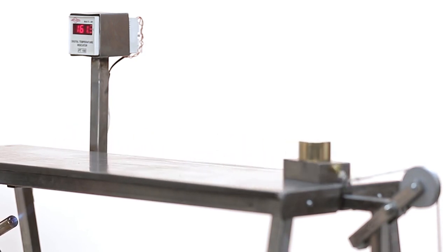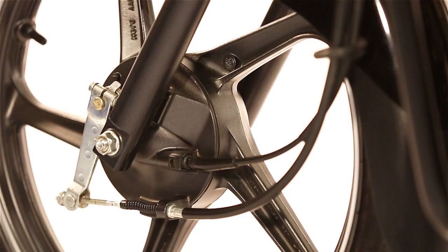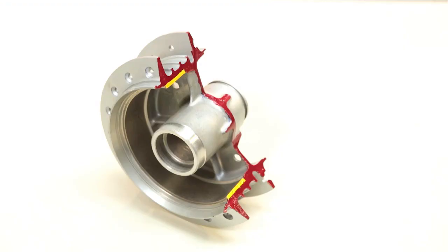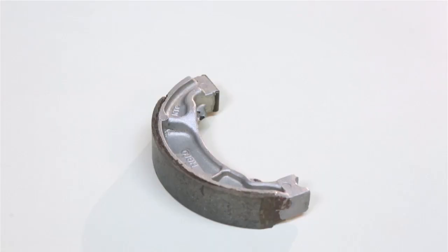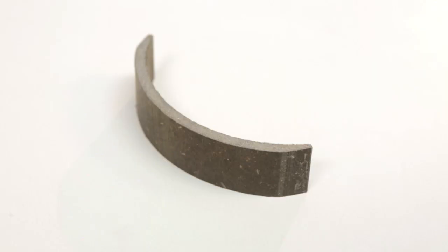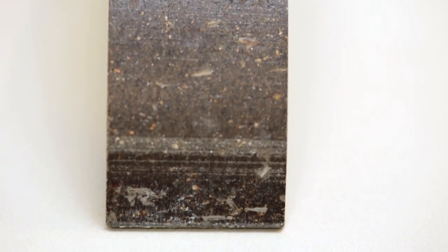This is described as fading. To prevent fading, the cast iron drum is cast welded into an aluminium hub for better thermal conduction. The brake lining is designed to provide good frictional force and not to lose this force even when hot. These are the anti-fading and anti-wear characteristics of the system.